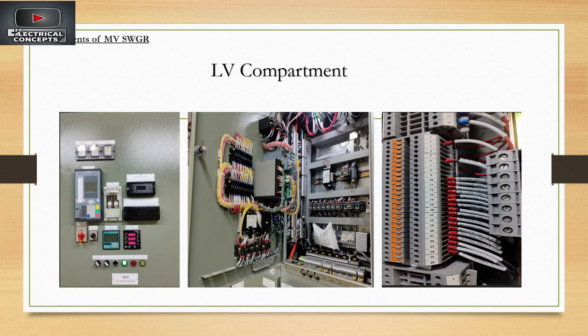Bay control will give you a choice to connect with the substation automation system, which is a modern technology to automate the substation. Before that it was RTU based. Now all modern substations come with the substation automation system. For the relays to communicate with it, they should be IEC 61850 SAS standard compliant. These units provide the facility to apply the desired protection to the system as well as the control.